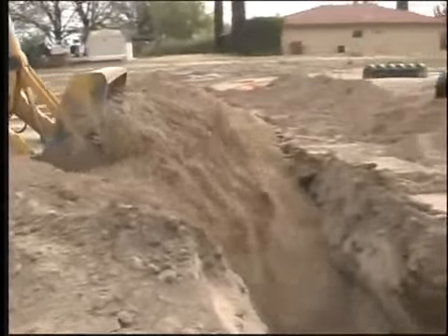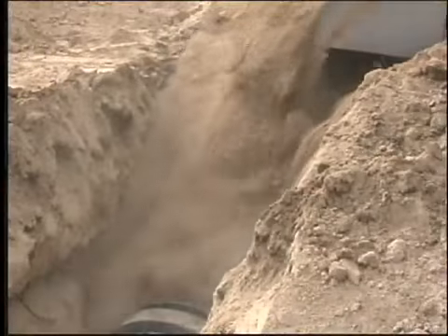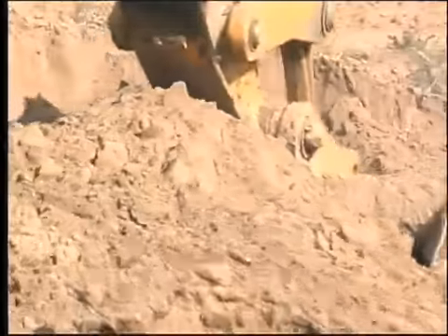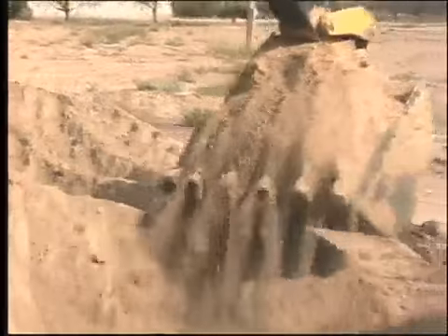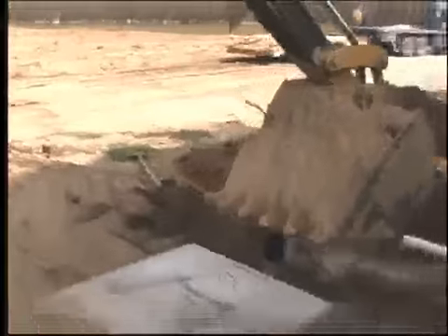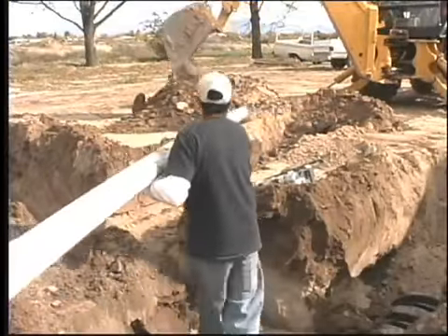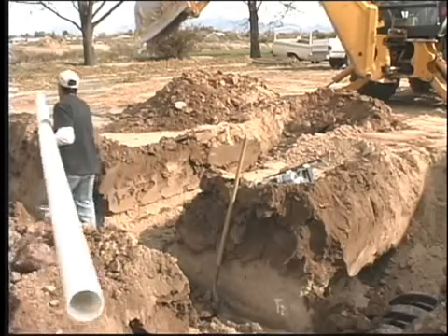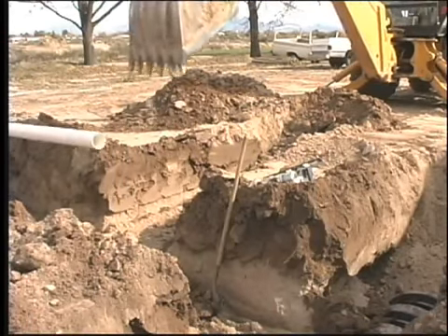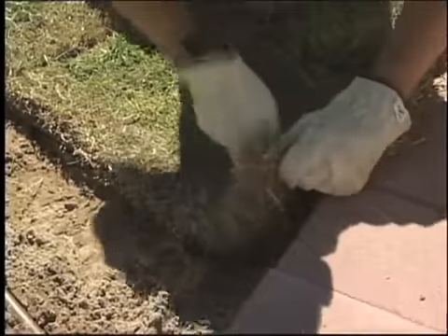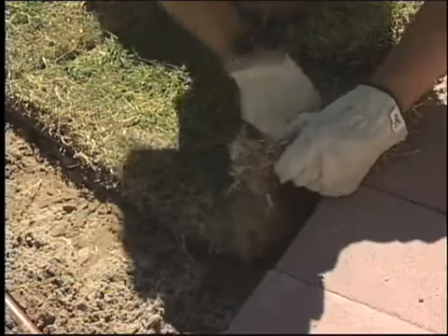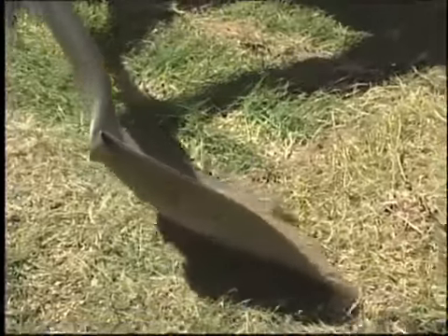For both the chamber and gravel and pipe drain fields, the trenches should be backfilled with the excavated soil and then smoothed off. Individual trenches can be dug and completed in sequence for ease of construction. Settlement may take 6 to 12 months. To prevent erosion, sod or seed the construction site immediately using grasses adapted to the area.